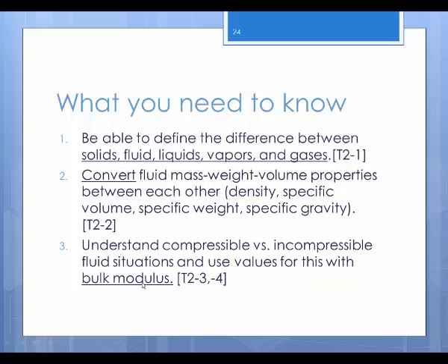I've just gone over a couple other topics. You want to know the distinction between these terms: solid, fluid, liquid, vapor, gas. You need to feel very comfortable converting between fluid mass, weight, and volume properties. You should memorize those different equations for specific weight, specific volume, specific gravity, and density. You should be able to just recall all four from memory. Understand what bulk modulus is, and how that's related to fluid compressibility as it changes with pressure.